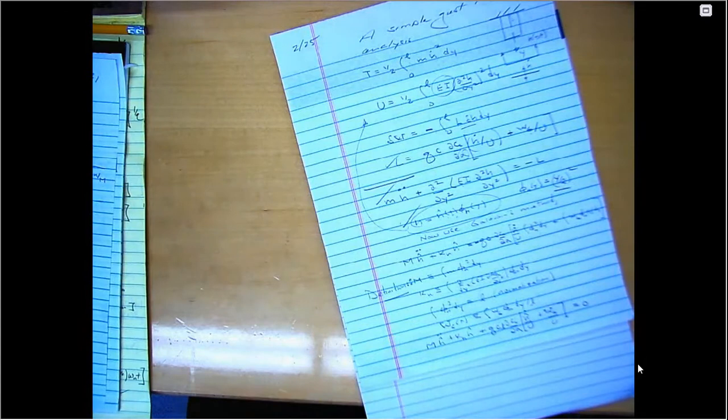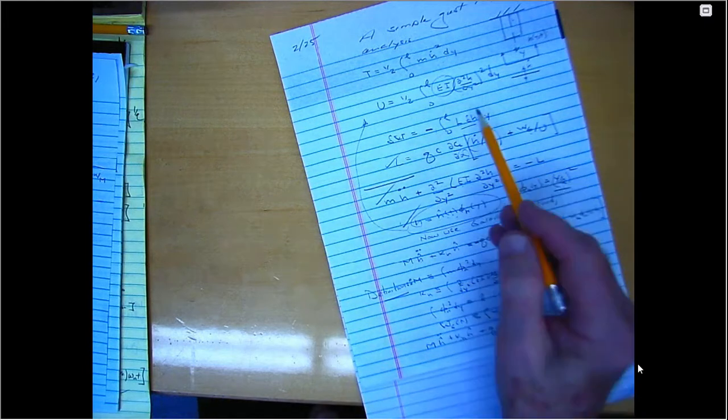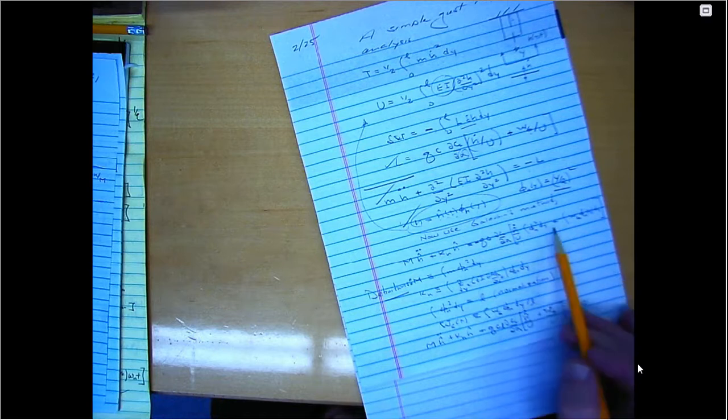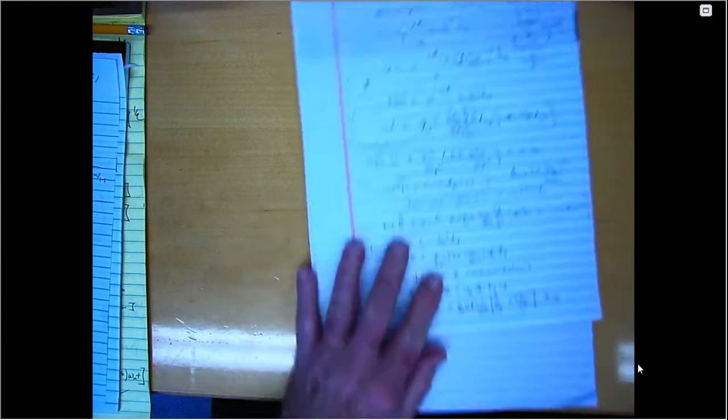Actually, Fourier is the one that's likely to be wrong. Why? Well, because in Fourier's method, there's no way of saying anything about the boundary conditions at the tip. Whereas in these other two methods, Lagrange's equations and Hamilton's principle take care of the so-called non-geometric boundary conditions, at least in an approximate way. And as the number of modes gets bigger and bigger, it does better and better in satisfying those boundary conditions. Whereas in Fourier's method, there's no mechanism for doing that. However, if you only use a single mode, as we've done here, then you do get the same answer.